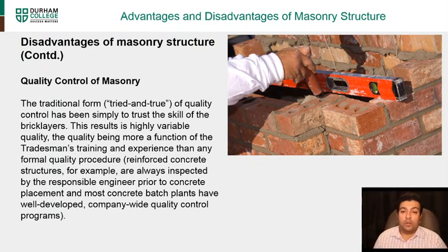You can also take core samples and test them, which gives you an equivalent idea of how much strength has been reached. With masonry, we don't have the ability to do certain tests. We can only see whatever is visible to the eye, some deficiencies, but other than that, it's all based on the skill of your laborer.